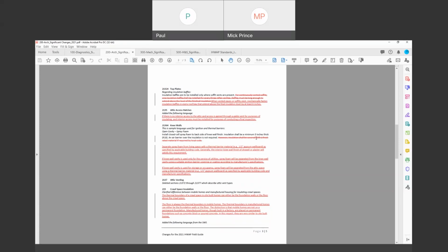Regarding attic hatches, sometimes the only access is through a gable vent, which is fine for a contractor insulating the attic. It makes it difficult, though, for an inspection and even if the client wants to get up there. So if that's the case, we're asking that an interior access hatch be cut through the ceiling.